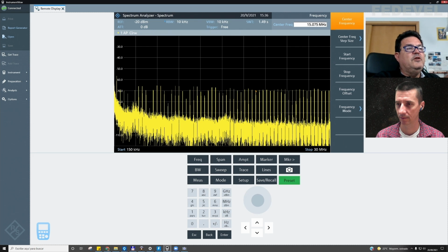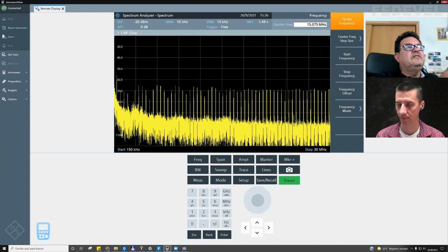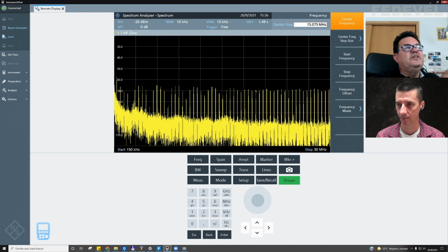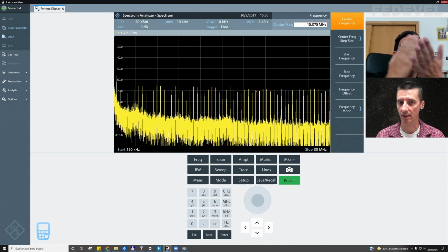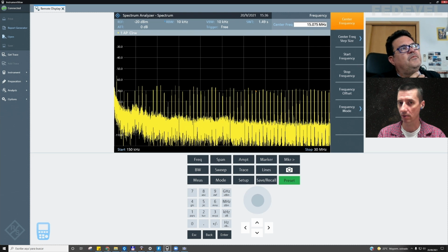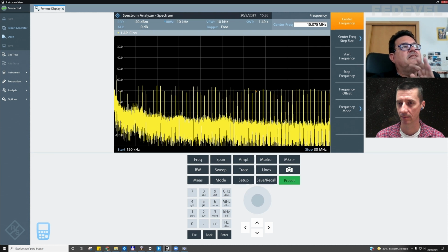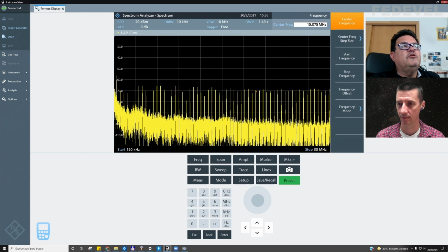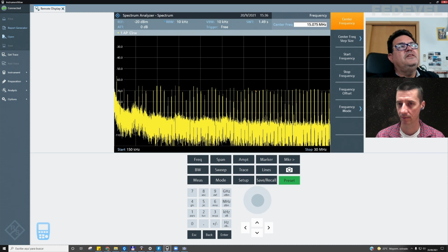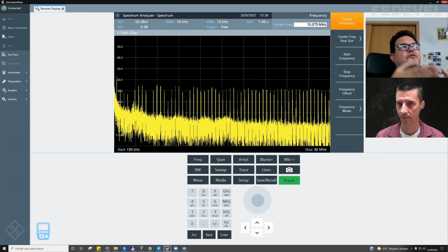That is because it's linear. You see that this axis is linear, so the distance from peak to peak is, I don't know, 200 kilohertz. And so this means it's all from one source? Yes, this is typical, no? From digital circuits, from switching mode power supplies, from someone that is switching at a constant frequency.